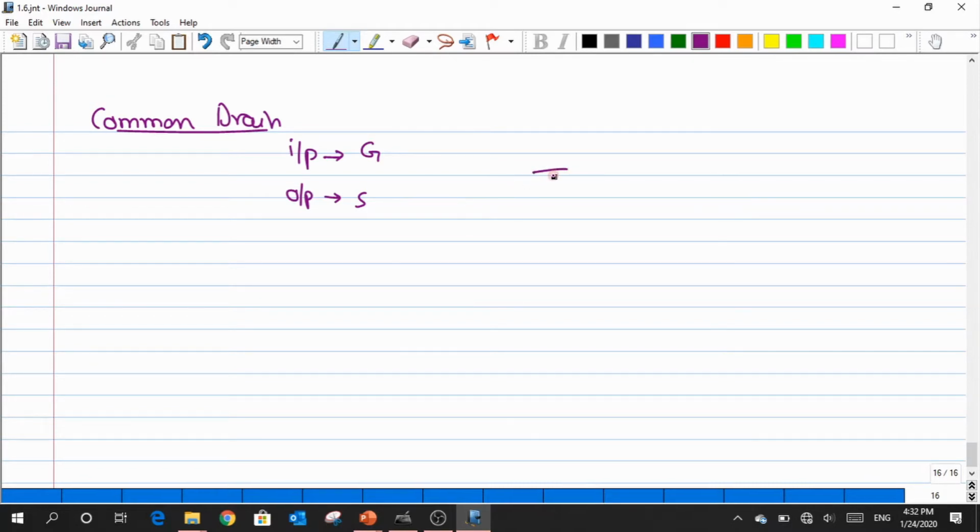So in short, if I'm going for an NMOS, then the drain will be connected to the capital VDD, and when I translate to a small signal model, this drain would translate as AC ground, right? So across the source, I have to tap my output. Whenever you want to tap an output, could this source be connected to the ground? No, because this transistor will generate only the ID. But if I want a voltage, you have to pass through a load, okay?